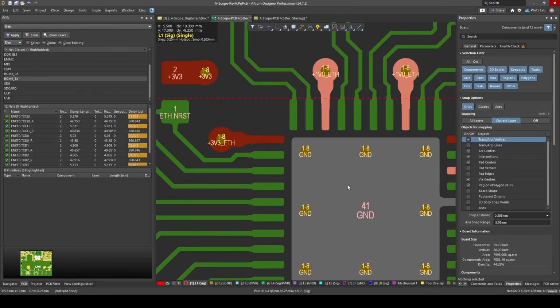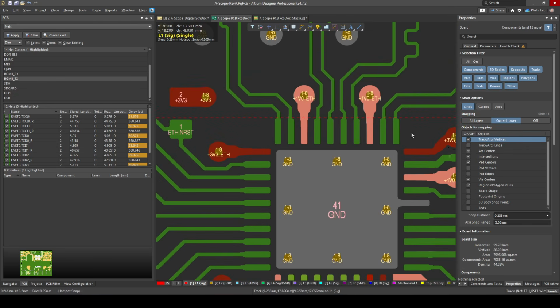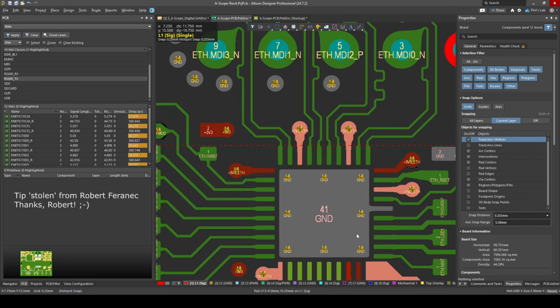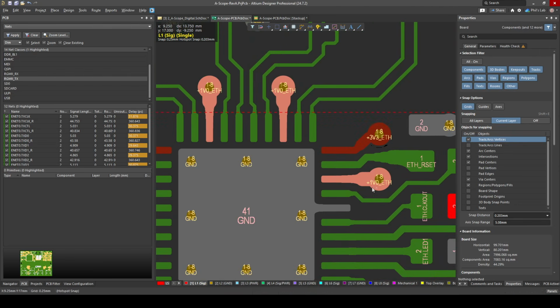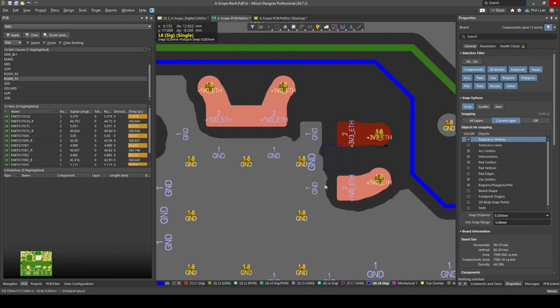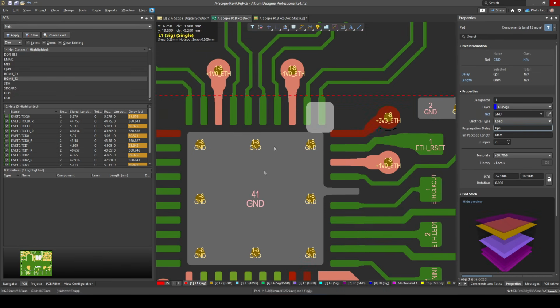Now, although this is not optimal from a decoupling standpoint, it makes my life a lot easier fanning out all these signals, and I think it's quite a neat little trick, and this seems to have worked well on many designs with QFN packages, even these high-speed Gigabit Ethernet physical layers. So I try to keep short wide traces, dig down with the via to the bottom side, place my decoupling capacitors so the ground pads face towards the exposed pad vias, and so I have my current loops like so.